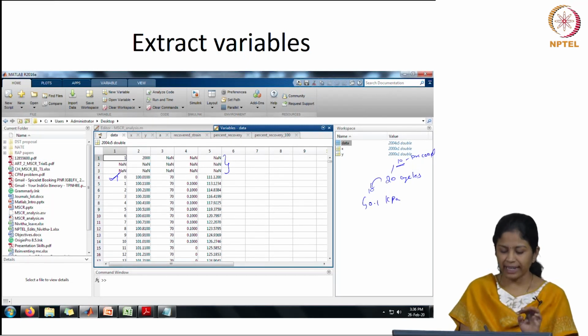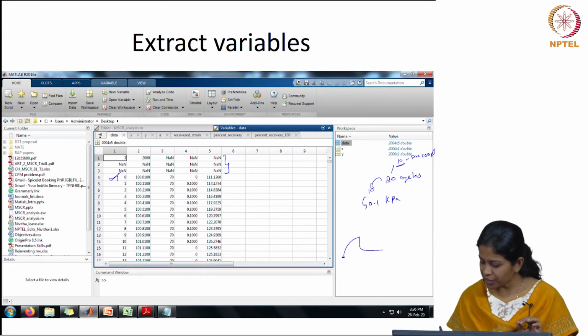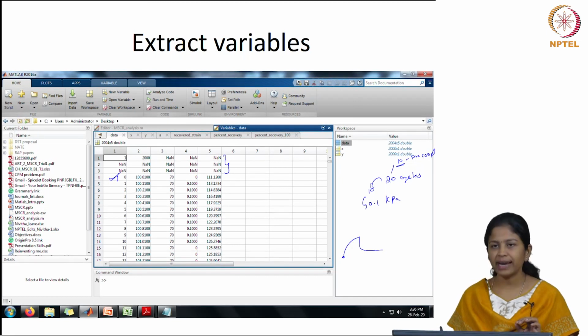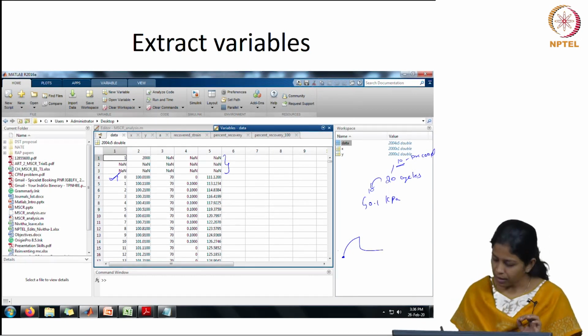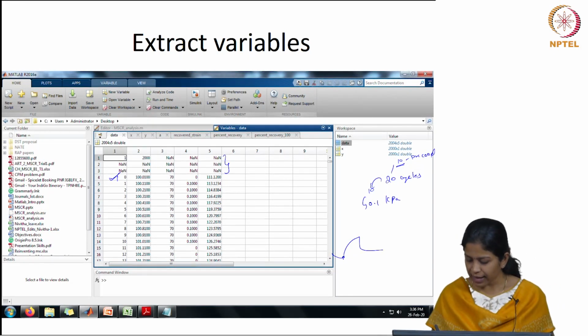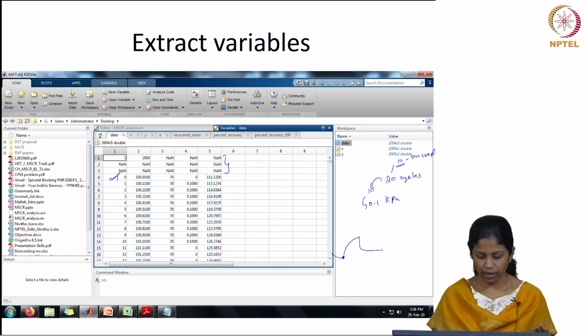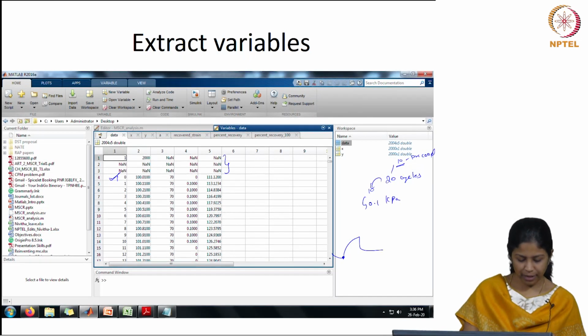You have to take this as the initial value, because in our creep and recovery test, this initial portion is the last data point corresponding to the recovery of the previous cycle. The previous cycle would have been recovering something like this, so this will be the initial portion for the next cycle. This data point we need, and that is shown here, right.